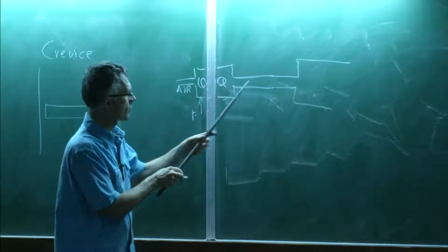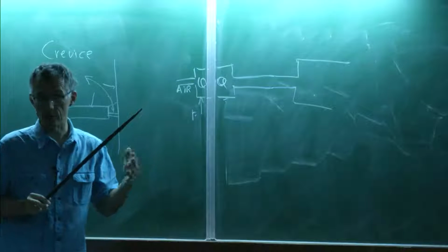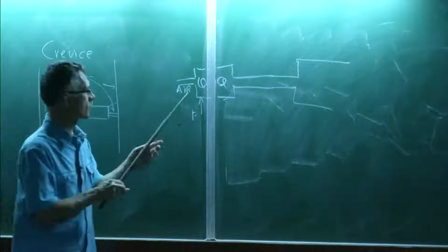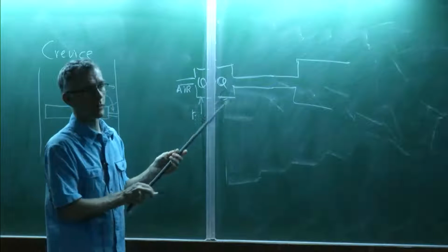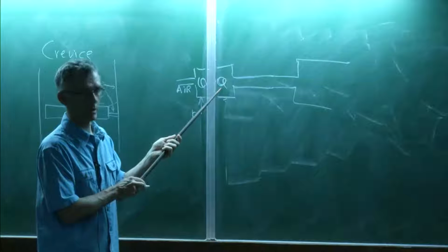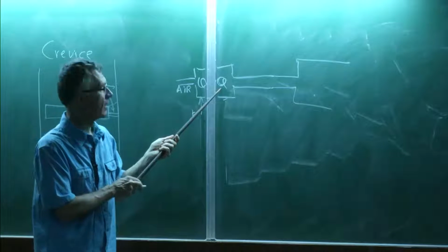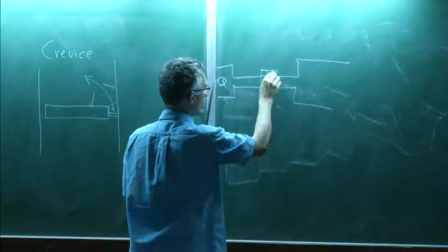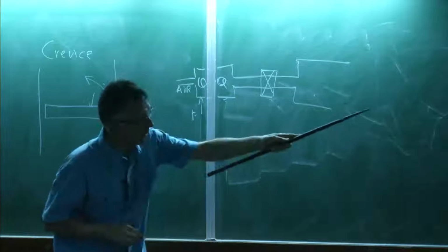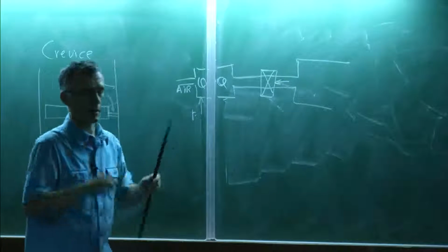You know that if the tube here is small, combustion will take place here at almost constant volume. This can be a 1 bar system, but if the flame comes here and explodes, you will go to 8 or 9 bars. This thing will go to 9 bars, it will explode, and we'll lose PhD students. So the way you do that, you put the flame arrestor here. You put this system here on the right-hand side, so that if the flame has the bad idea of coming up here, it will stop.